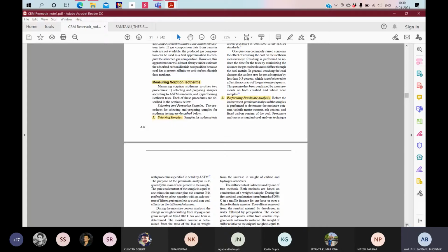Now if you are going to drill 10 different boreholes and intercept that particular seam at different depths, and you are going to take the core logs, and from the core logs you do the routine analysis for porosity, permeability, strength, density and many other properties, there is an obvious chance that these values will be different, even if you have taken the samples from a single coal seam.